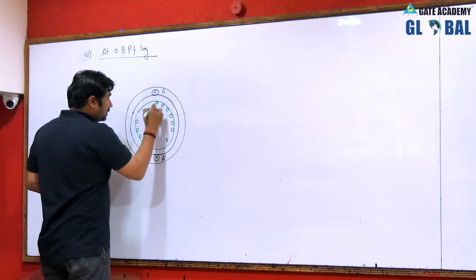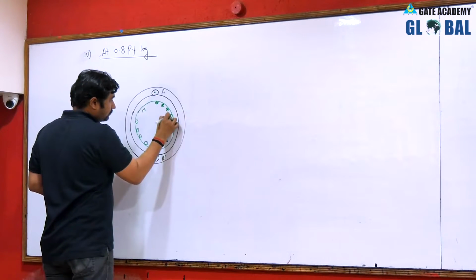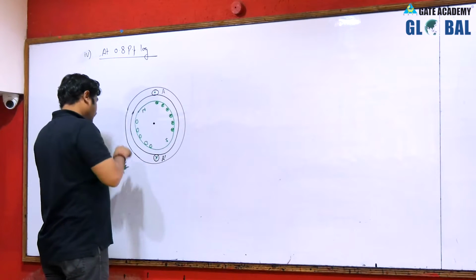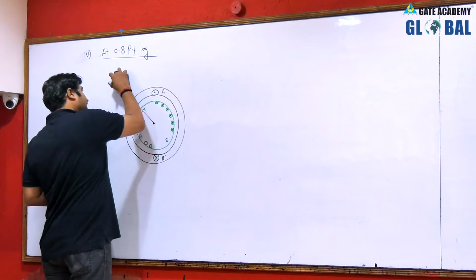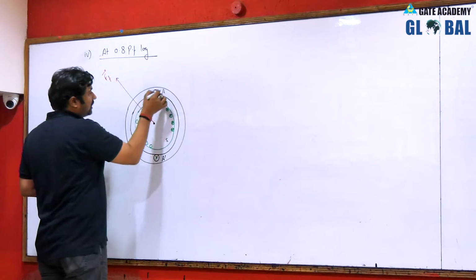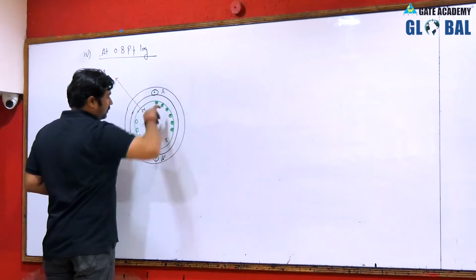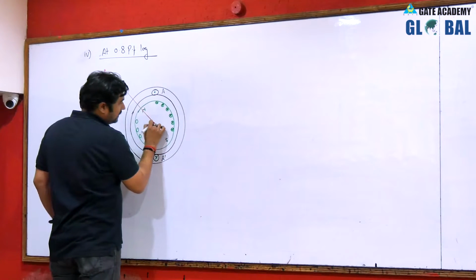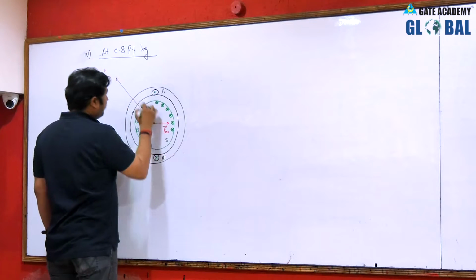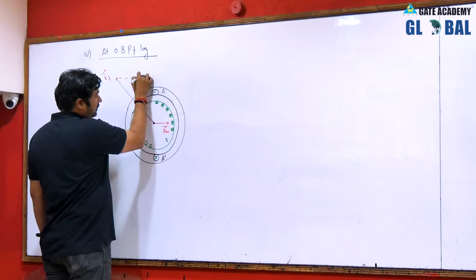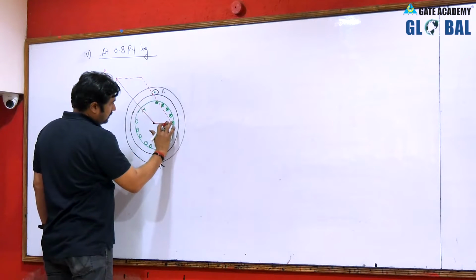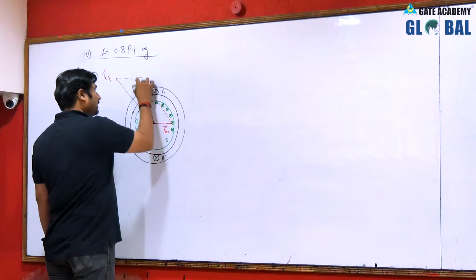Is it okay? Now, this will be your rotor field. Please observe, that is the main field FF, and because of the current flowing in the armature, this will be your armature field, FAR. So if you find the resultant of FAR and FF, the phasor sum of these two is directed somewhere at this point.